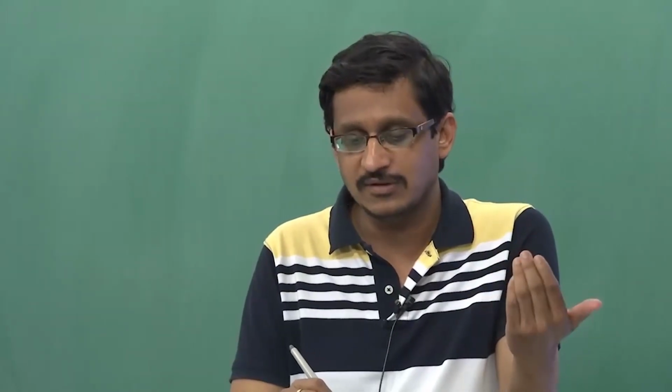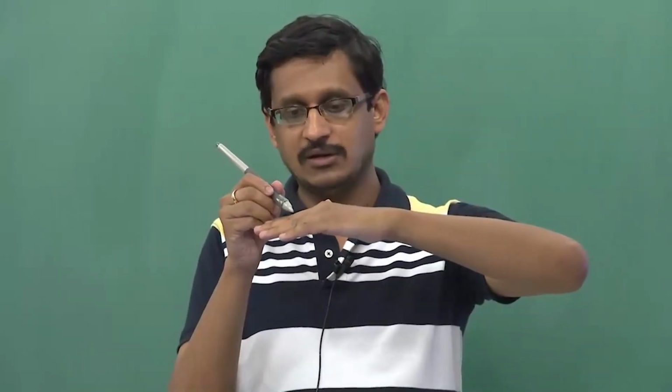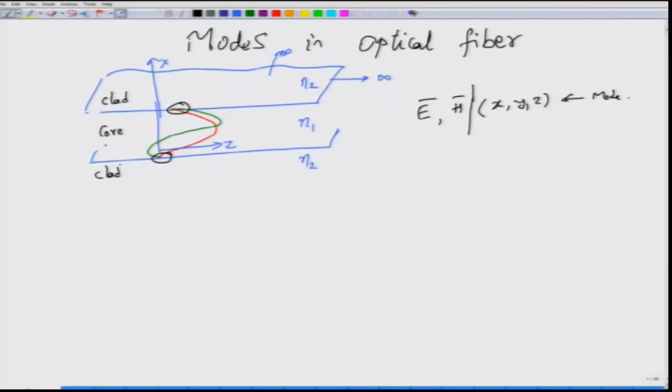So, what you see is that within the guided region, or within the region of the slab, you will expect a half sine wave, 1 sine wave, 2 sine waves, 3 sine waves and so on, multiple higher order modes. At the edge, where you are meeting the surrounding region, the field does not really go to 0 there, but rather it extends into the region surrounding the guided region, right. If we call this guided region the core and the surrounding region the clad, this is called a symmetric slab waveguide because N2 is the same on both sides surrounding the region N1.